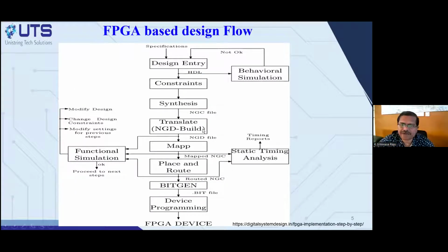If you go deeper into the FPGA, you do design entry, and there are something called constraints. You apply pin constraints because the FPGA as a chip has multiple banks. These will all be taught in the course. Each bank has some constraints. Some banks work with some power supply, some voltages.